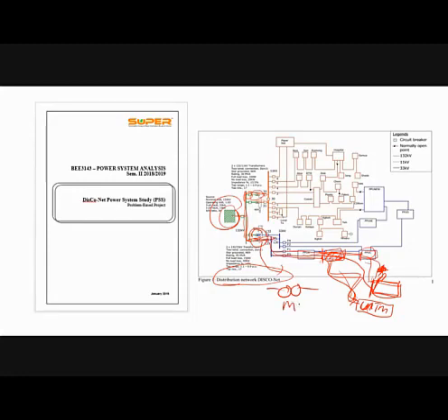That's why for a transformer we have MVA, right? This MVA is actually the capacity of the transformer. Transmission lines also have a capacity for current flow. What is the current flow in this line? Can this cable withstand the maximum current flow when the new load is connected to this line? So that's why we have to do the power flow.